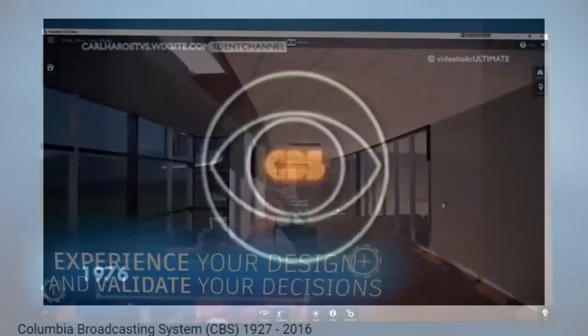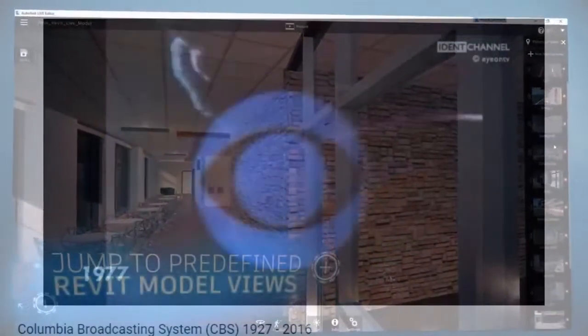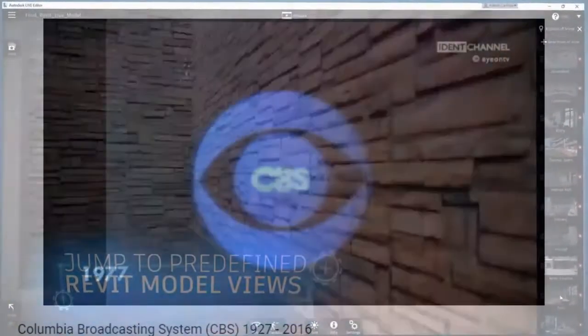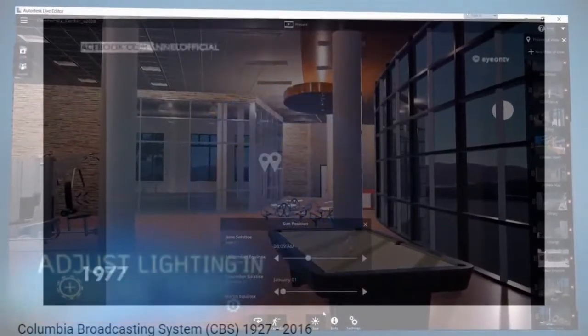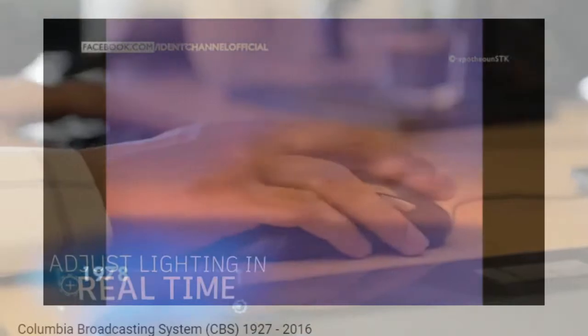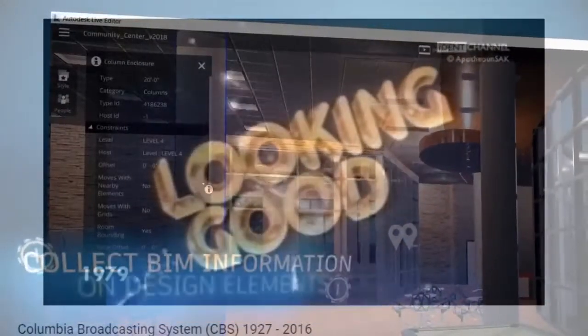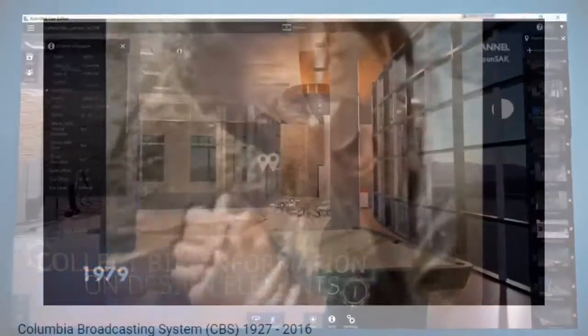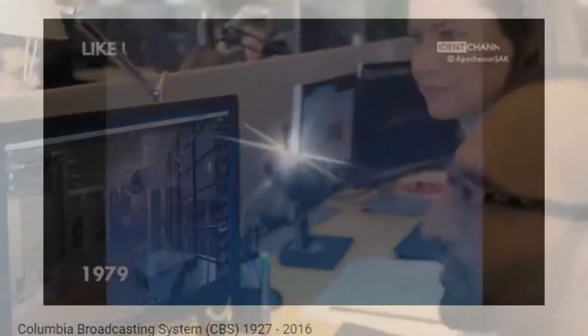So if I go to level 1, and I go by COBIE over here, and I take slab depression, I drag it in, I'm going to get these witness lines, or these dynamic dimension variable lines, dynamic snap tracking, if you will. And I'm just going to place it next to COBIE, and I'm going to drag it down, and it just stops. It's inserted, and as you can see in the properties palette, there's the slab depression.